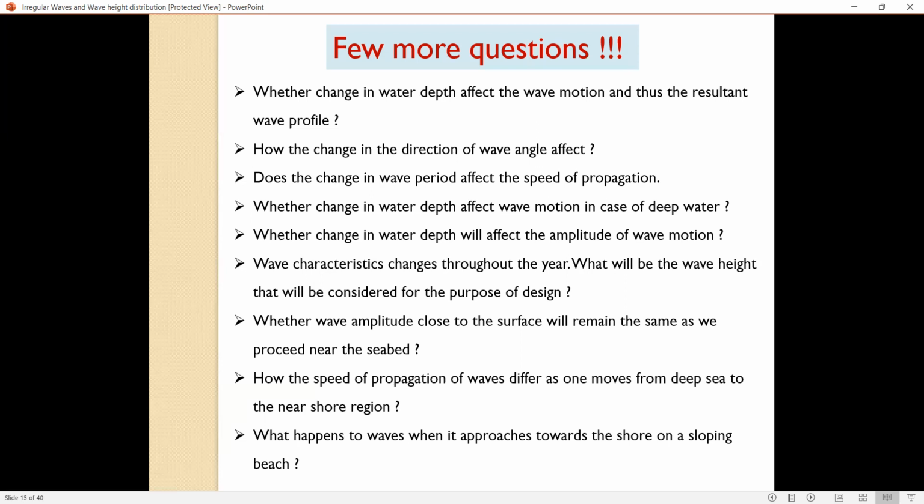In fact, by looking at how much energy it will reflect and how much it will transmit. To understand that problem, the floating breakwater, as I have told you, he considered as a line, like a breakwater, a surface piercing object fixed at a point, and then a wave is propagating. So wave scattering by a surface piercing breakwater was first studied in 1947, just after the Second World War. And that concept came because he said, okay, I consider this as a one-dimensional object in a two-dimensional fluid domain. And that was the first problem on wave scattering.